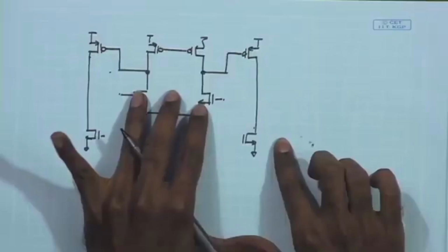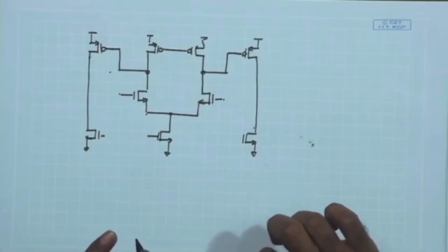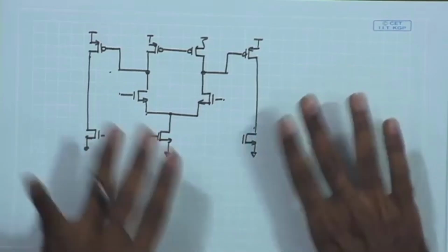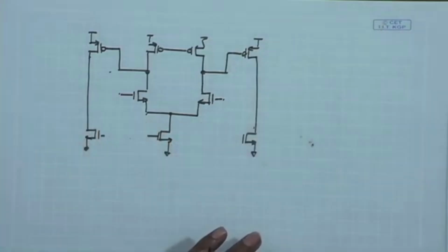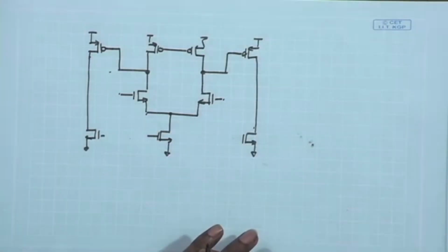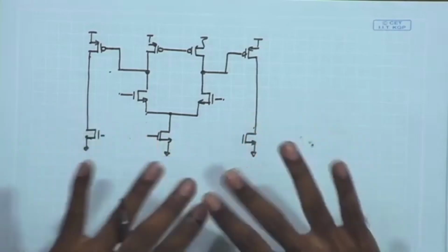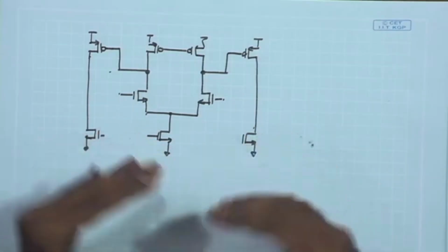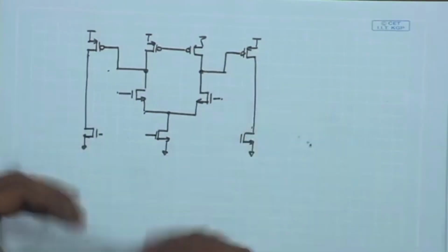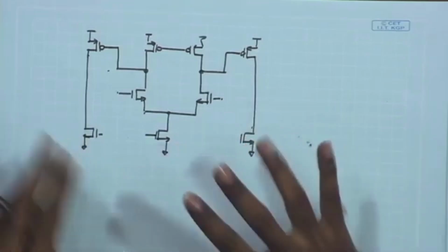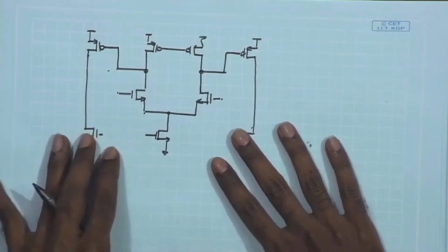So, I will discuss the circuit implementation for the dual loop common mode feedback, where you are having two separate common mode loops for the first and the second stage of the op amp. We will try to contrast this method with the single loop compensation that we discussed, and understand the pros and cons of both the methods, and some of the details that we skipped earlier, the transistor level implementation of the dual loop common mode feedback. We will go a little bit deeper into that and finalize the implementation, which will be useful for your simulation exercise.